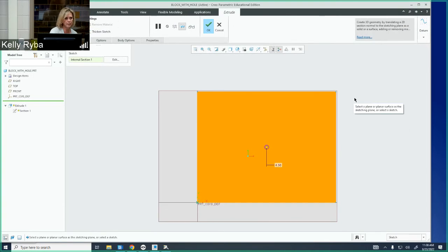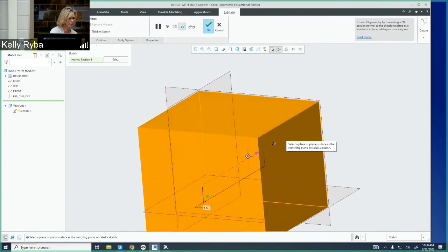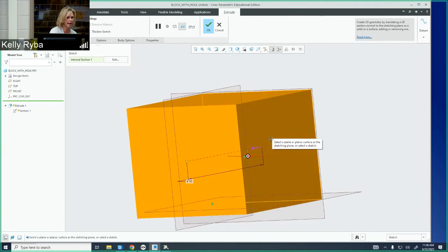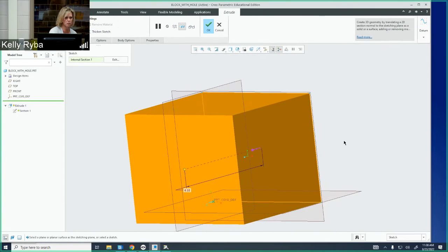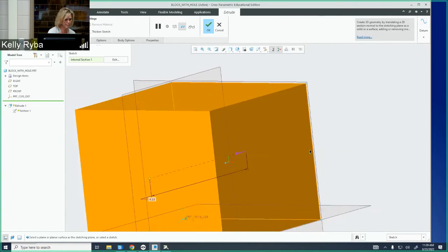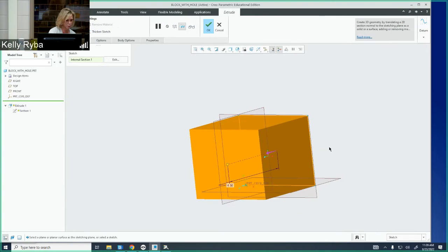I'm going to take my middle mouse button and I am going to depress it, hold it, and I'm just going to rotate or drag it around a little bit. And now you see how I'm changing, and I can kind of see now that third dimension, okay? And I'm going to rotate my roller towards me without depressing it or away. Away is going to be zooming out a little bit so I can see what's going on here. All right. It's like, okay, I know you want to extrude, but how far do you want to extrude? I've got to give it information.